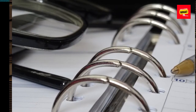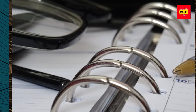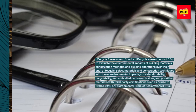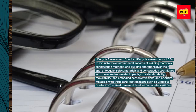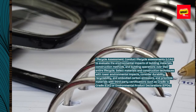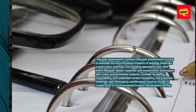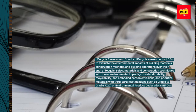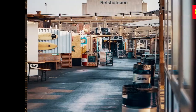Life cycle assessment. Conduct life cycle assessments, LCAs, to evaluate the environmental impacts of building materials, construction methods, and building operations over their entire life cycle. Select materials and construction techniques with lower environmental impacts, consider durability, recyclability, and embodied carbon emissions, and prioritize materials with third-party certifications such as Cradle to Cradle, C2C, or Environmental Product Declarations, EPDs.